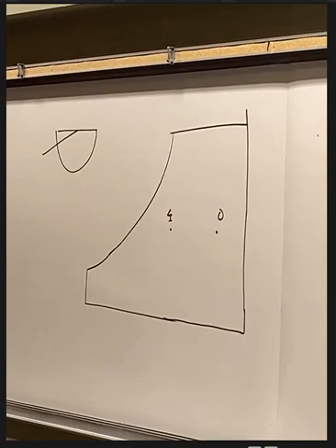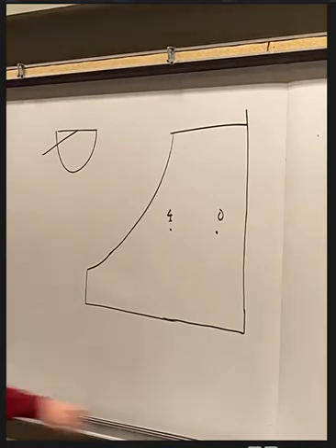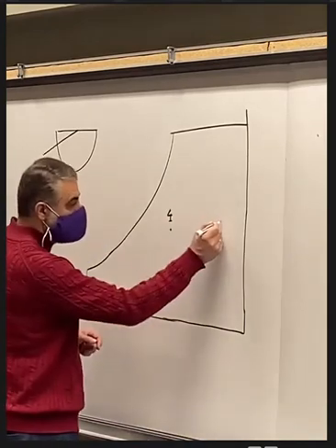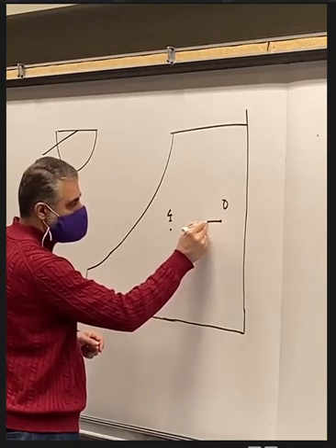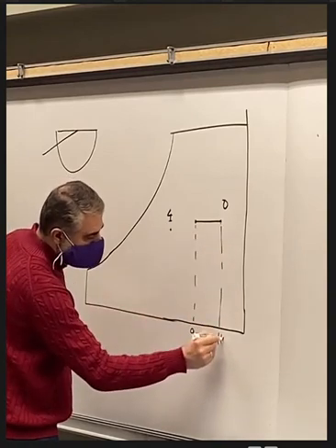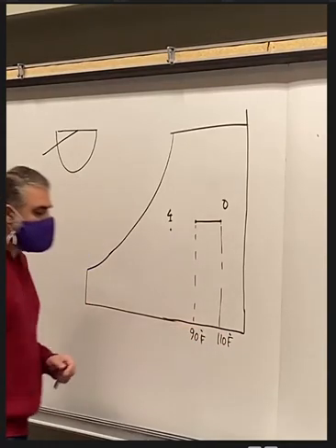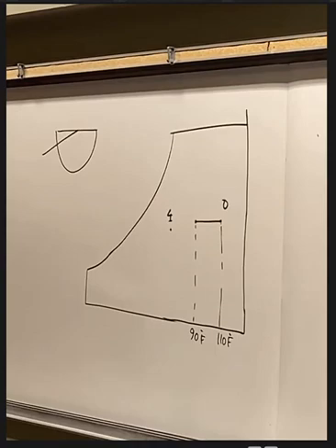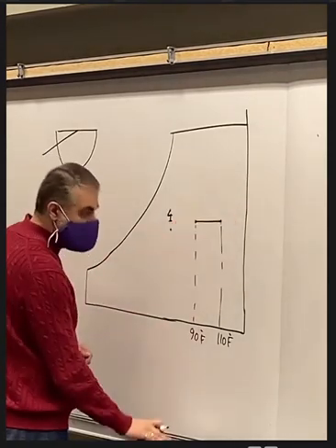So the heat recovery will reduce the fresh air temperature by 20 degrees. So it will leave at 110 minus 20, which is 90 Fahrenheit. So this is point number 1, 2.